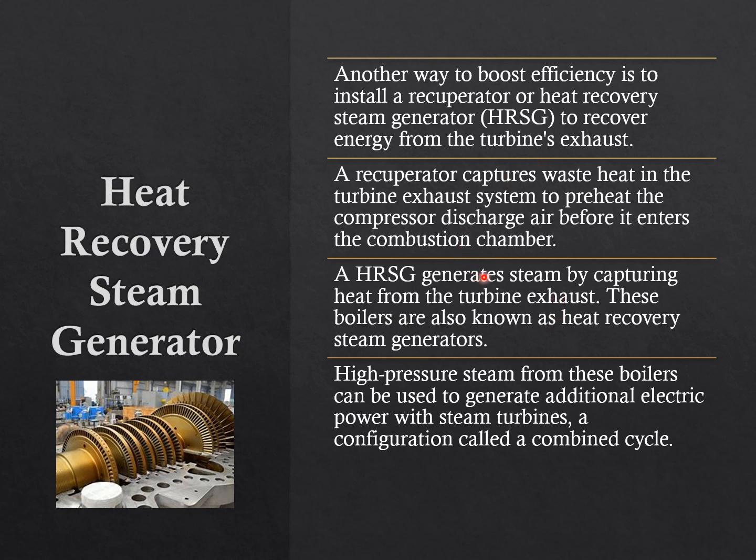So this approach to boost efficiency is nothing but the first one, a recuperator, and the other one is HRSG. That's your heat recovery steam generator, and we call it HRSG. This is going to capture heat from your exhaust, the same thing as a recuperator, and then it's going to produce the steam.